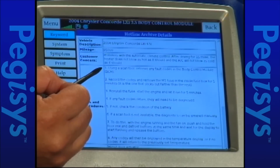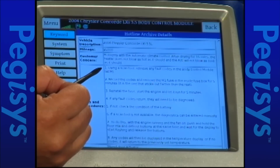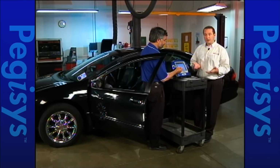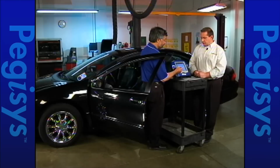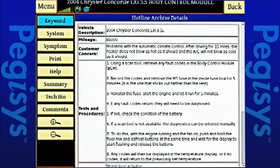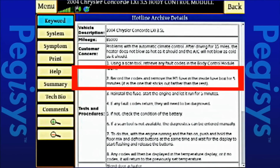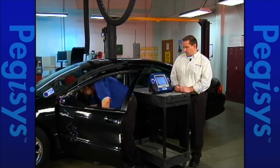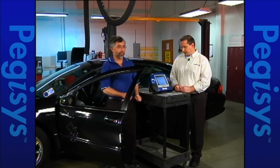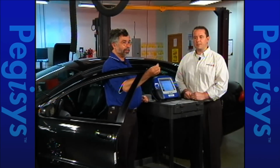Sure. It looks like our first step here is, using a scan tool, retrieve any fault codes in the body control module. And of course, we've already done that step, knowing ahead of time that the BCM does control the climate control on this vehicle. So let's go down to step number 2, and it says record the codes, of course if you retrieved any, and remove the M1 fuse in the inside fuse box. We're going to record the trouble codes and remove the M1 fuse in the inside fuse box for 5 minutes. It is the one sticking up further than the rest in that particular fuse box.